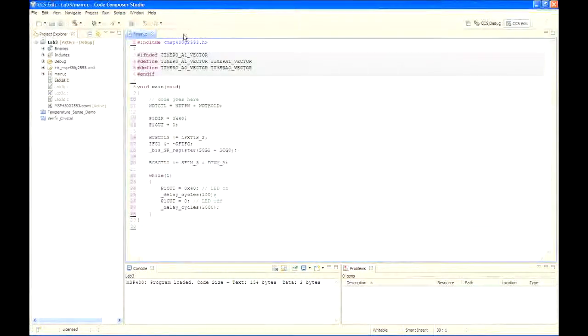In step 32, we could just let the DCO run, but let's go ahead and calibrate it. Right after the code that stops the watchdog timer, add the following code that you see in the workbook. And you'll see it added on the screen here.